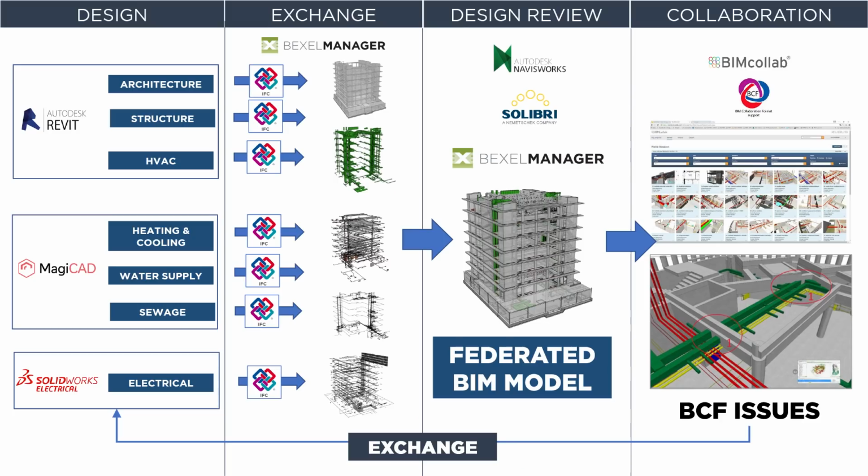Some BIM software solutions support importing spreadsheets like this and instantly enriching the BIM model with all needed data. When it comes to file format, most BIM execution plans will require companies that are working on projects to use the IFC file format to exchange BIM models between different software and applications. Now, Industry Foundation Classes, or IFC, is the platform-neutral file format developed by buildingSMART, and it's a primary